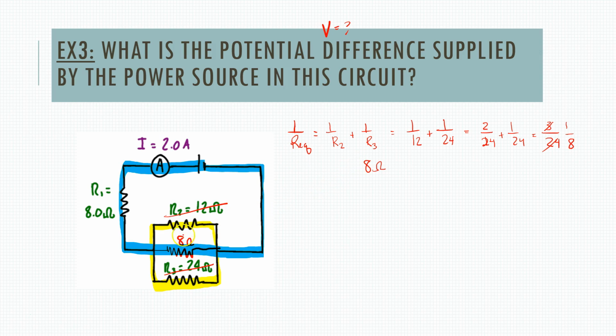I can either figure out the voltage that is going through the individual pieces and add it up, because in series, remember, your equation for voltage is that it's voltage 1 plus voltage 2 plus voltage 3 plus voltage 4, etc. Or the other option is that I can put it into V is equal to IR like we've been doing and use our totals for the whole thing. I personally believe that the easiest way would just be to plug it into V is equal to IR.